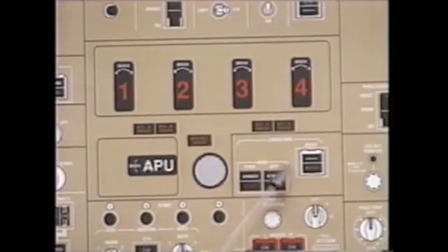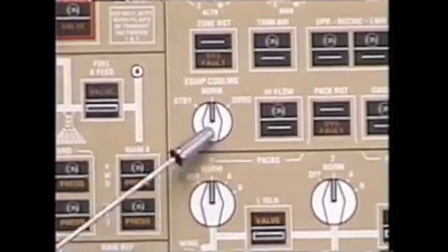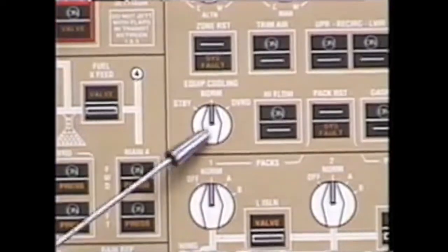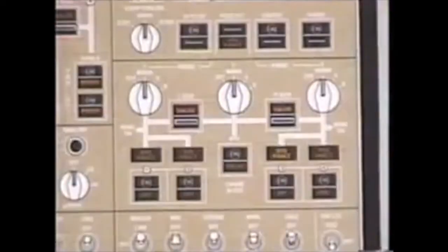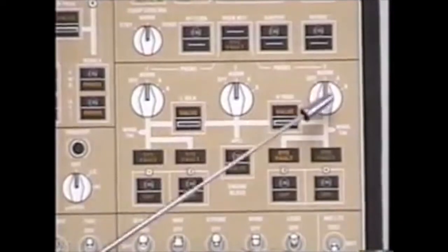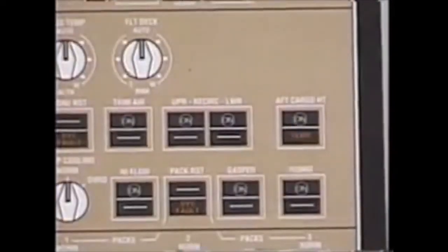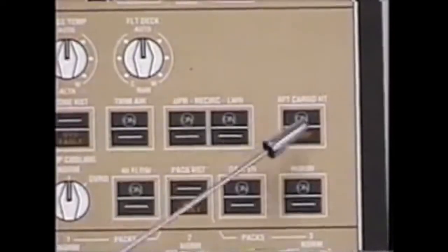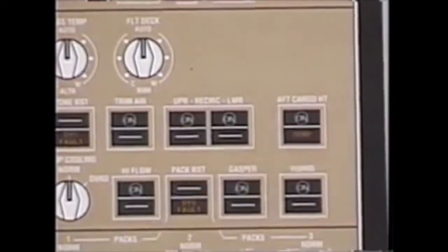Lower cargo, there are 4 bottles in that system referred to as bottles A, B, C, and D. Arming of a cargo fire button, either forward or aft, will accomplish 4 things, regardless of which switch you push. Arming either forward or aft will arm all 4 fire bottles, shut off all fans on the airplane. As a result of shutting off the equipment cooling fans with that group, equipment cooling will automatically go to override, as well as shut down pack number 3. In addition, arming the aft cargo button will also shut off aft cargo heat regardless of this switch position.